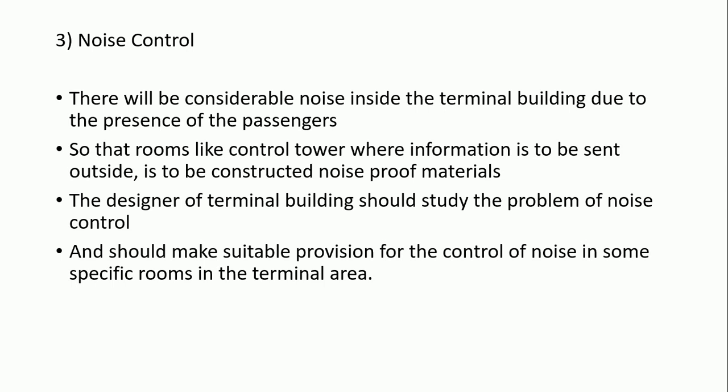Now we are talking about noise control. There will be considerable noise inside the terminal buildings due to the presence of the passengers, so rooms like control towers, where information is to be sent outside, should be constructed with noise-proof materials. The designers of the terminal building should study the problems of noise control and should make suitable provision for the control of noise in some specific rooms in the terminal area.